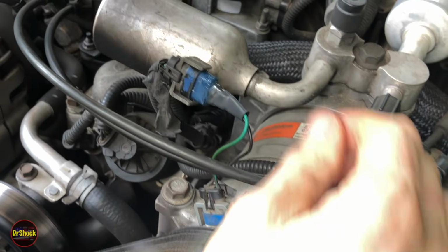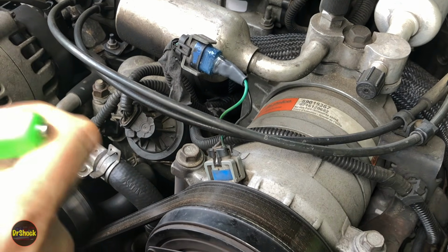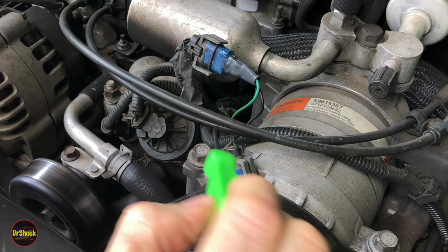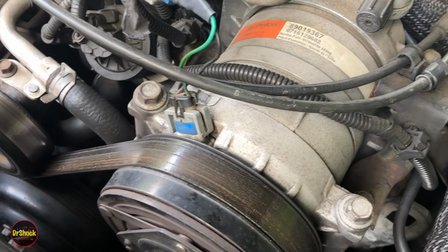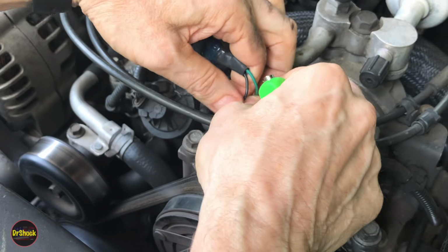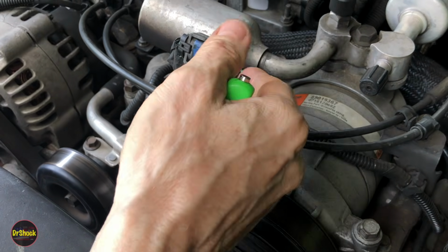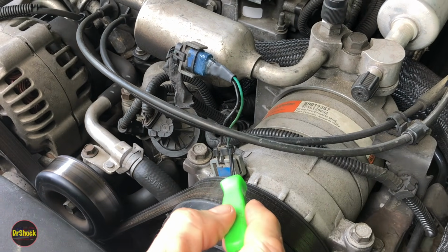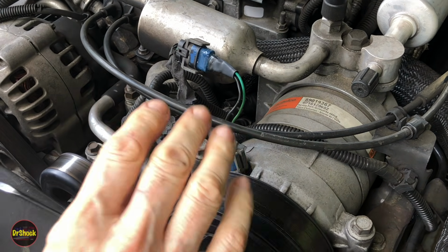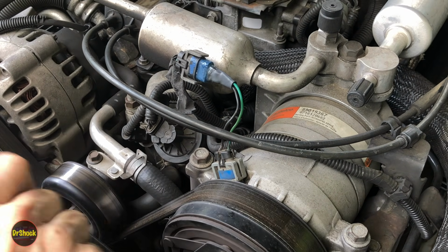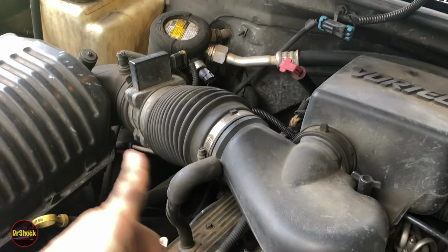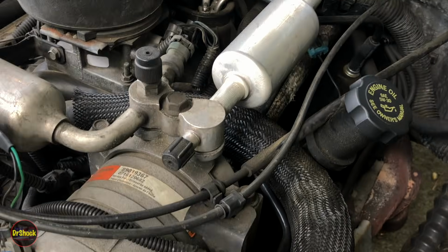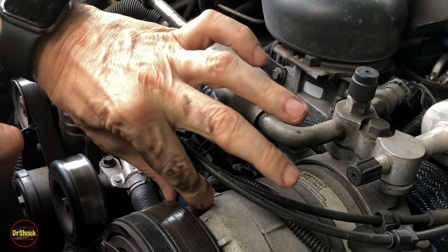Now, why are we doing this? Well, for two reasons. One, this will help me eliminate the possibility of either this connector or the electromagnet connector being part of the problem, and it'll also give me a place to attach some piercing probes to monitor the circuit from inside the vehicle while we're driving. When this cuts out while we're driving, we want to be able to see on the scan tool what's going on with these switches that I pointed out before, as well as that relay. And then we're also going to want to monitor what's happening with the power being supplied to this electromagnet.